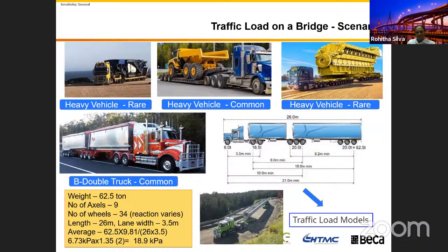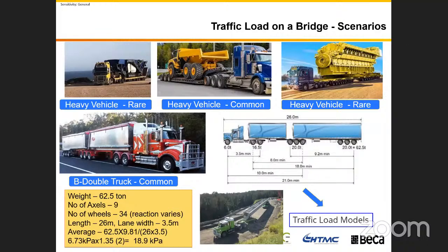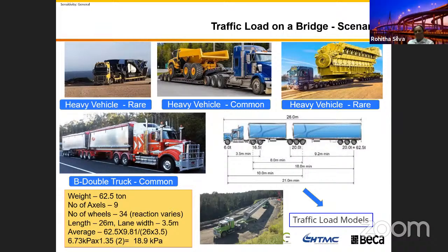Did I answer? Yes, thank you very much. And I just thought, if it is a continuous bridge, then because of the alternating arrangement of bending, there might be some worst cases with the given span, where with two vehicles, one span could have higher bending than with a normal single truck. This is what I would further add.